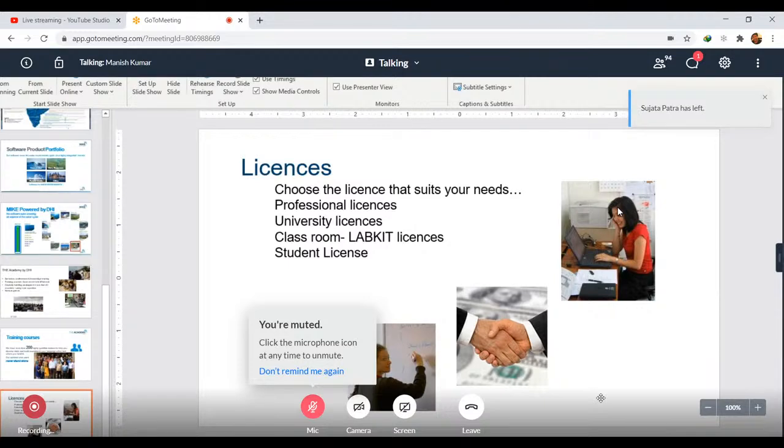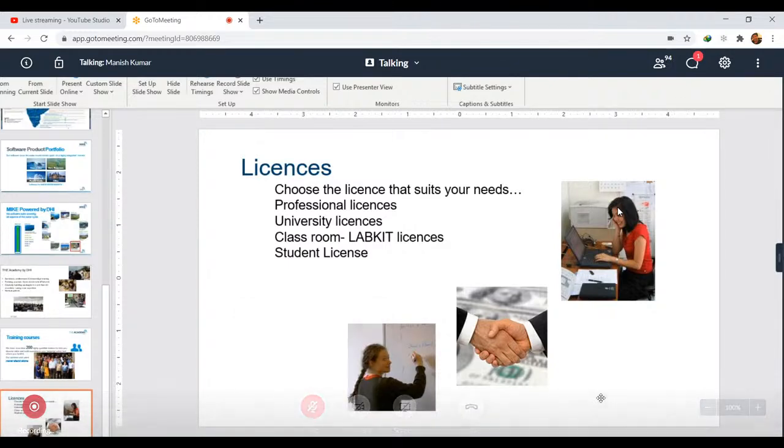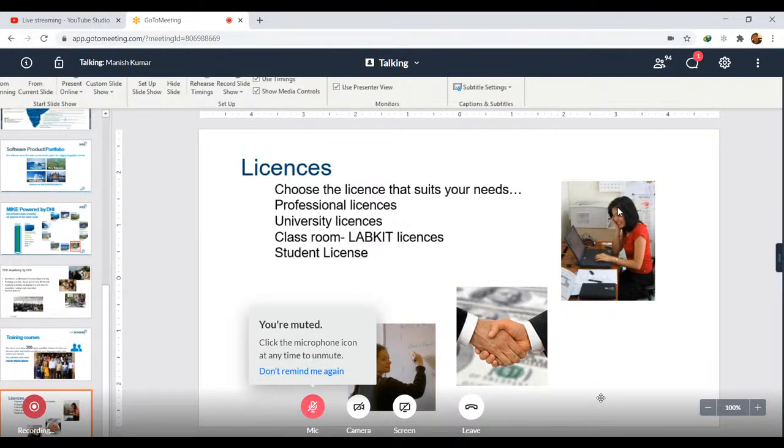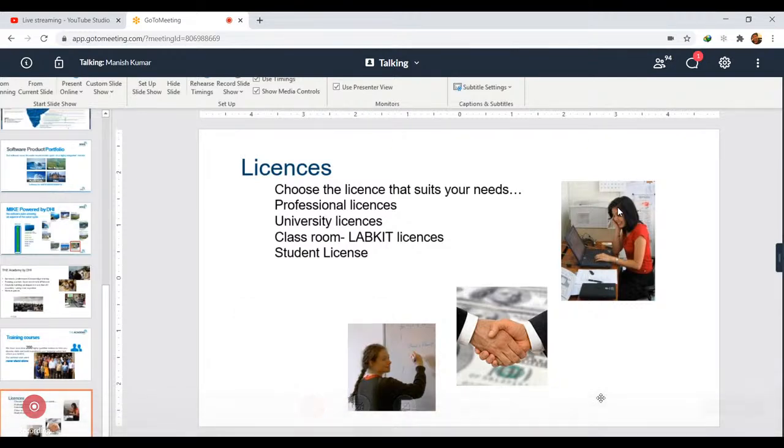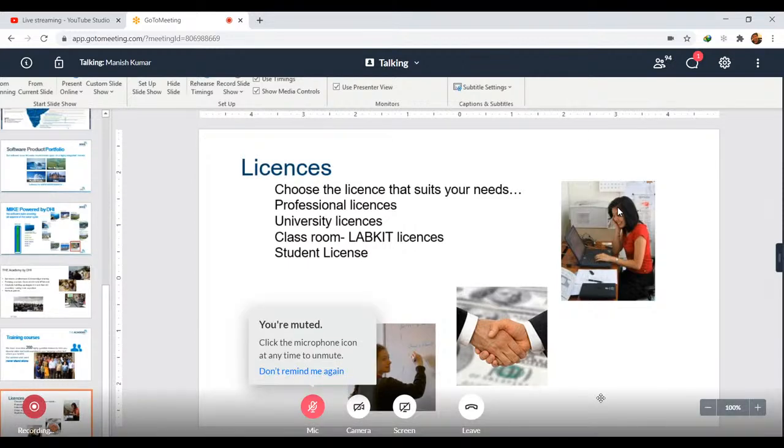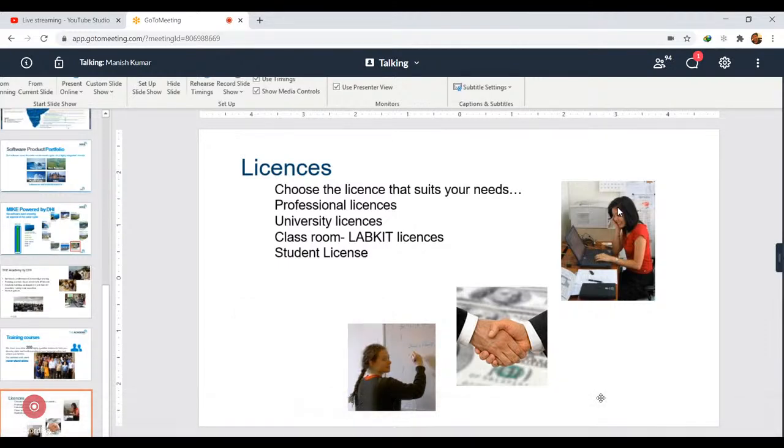You can create shape files from KML file and shape file using Google Earth Pro, create building shape files, and give the elevation values there. You can update your downloaded DEM using this information. This way you can get information from various sources and update your model with whatever information you have. Ultimately, surveyed information is the best information that you need.